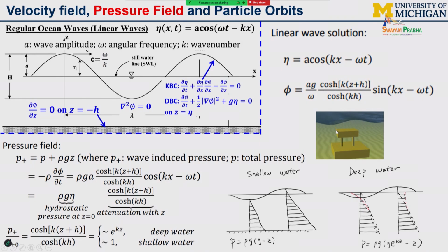Some companies, like Carnegie Wave in Australia, develop wave energy converters submerged into the water. Actually for military applications, you don't want anything outside the surface, right? So you submerge it into the water. This cannot be too deep. If it is too deep, the dynamic pressure decreases too quickly, right? It's the same pattern, e to the Kz. Therefore, you try to keep it as close as possible to the surface, but submerged into the water.